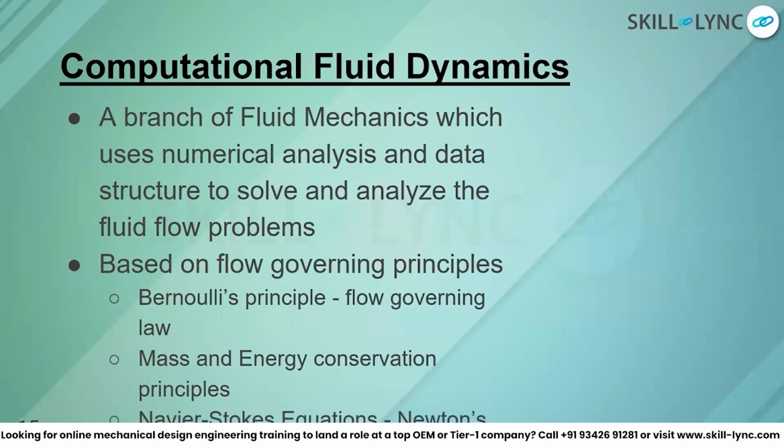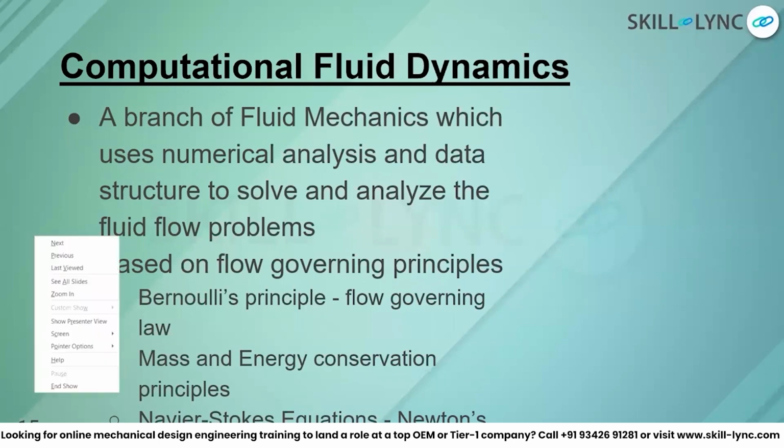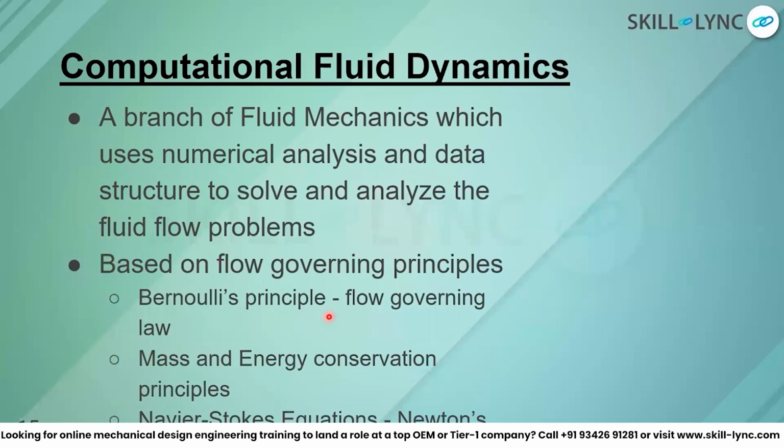Okay, so the important thing is these equations are based on the Navier-Stokes equation, which is basically based on Newton's second law. So collectively we can say the Bernoulli's equation, which is basically a flow governing equation, mass and energy conservation principles, and Navier-Stokes equations. These are the three major ones, I'm saying only major. There are many laws and many schemes implemented in computational fluid dynamics, but these three or four are the backbone.